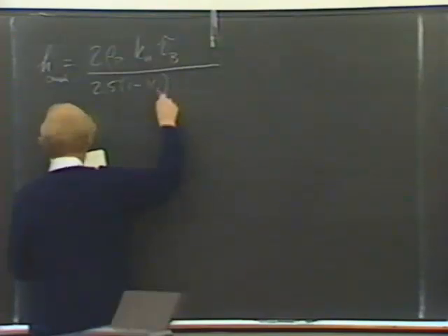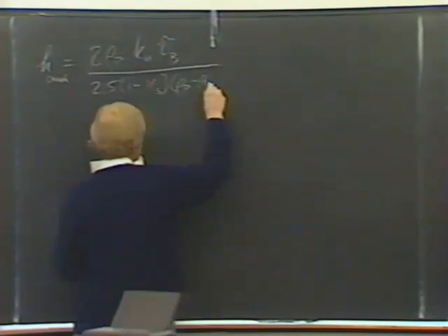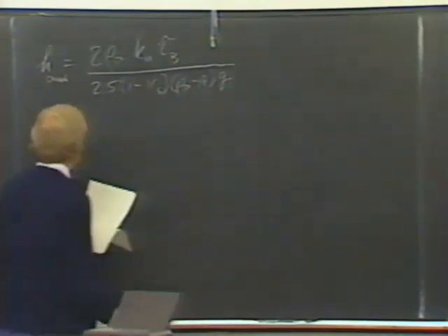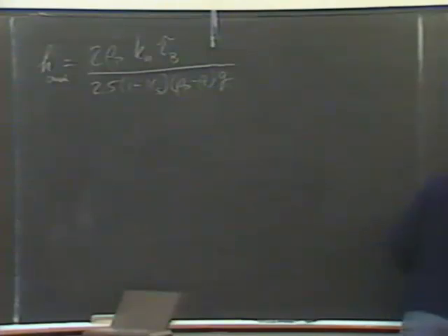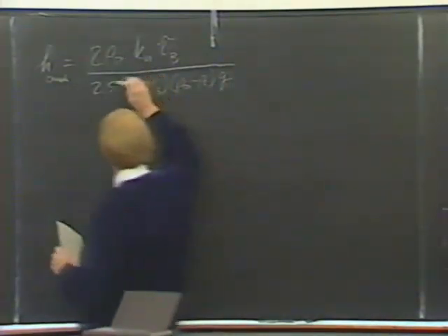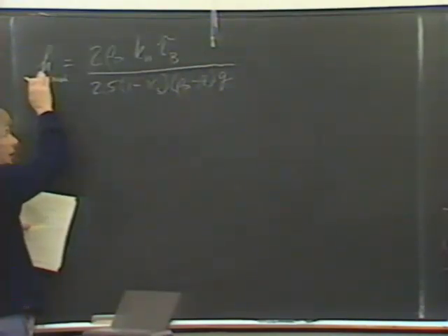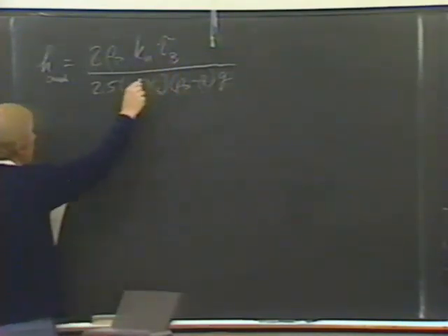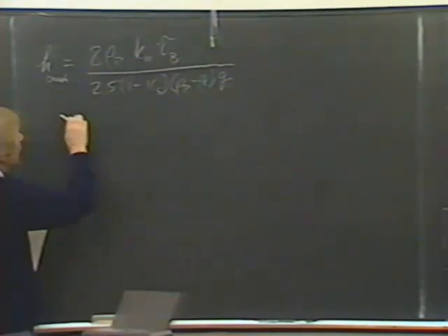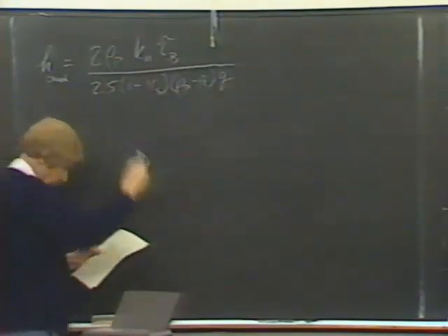What I did was to substitute this back into this relationship, and then solve for H, and say that the height where it crushes is the height where it fails, using tau sub b, the Bingham shear strength, for the tau. That's the only change for tau, and that'll give us the depth for crushing. From the flume data, measuring the depth of crushing, and I'll show you that in just a minute, we found that K sub s is about 0.93.